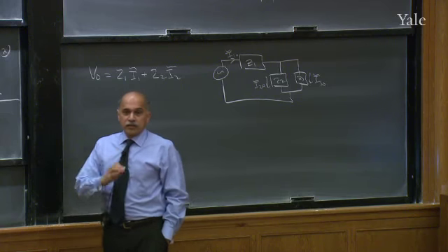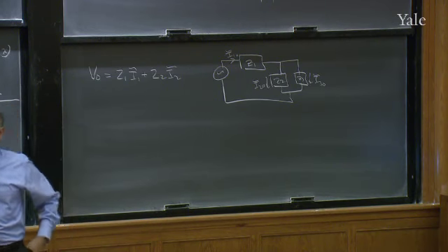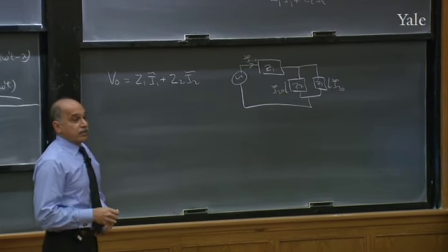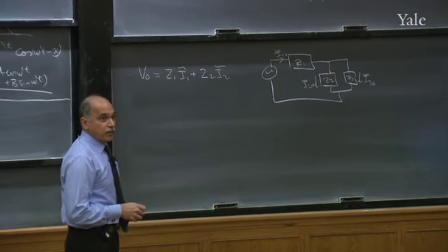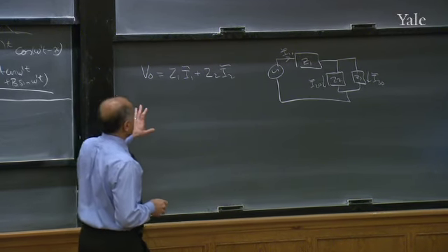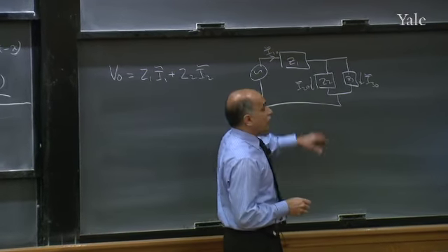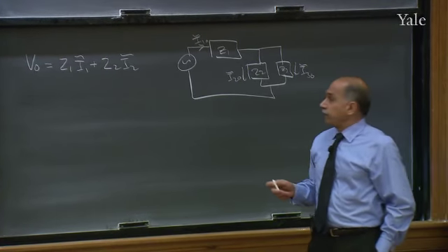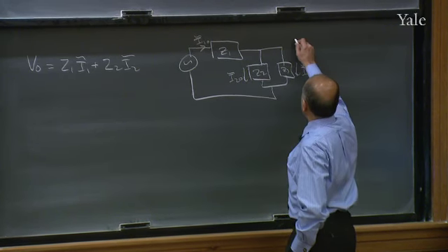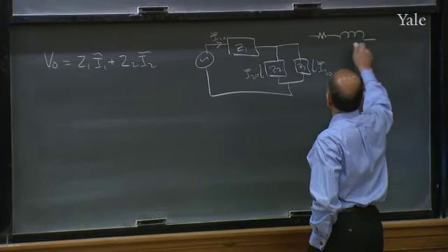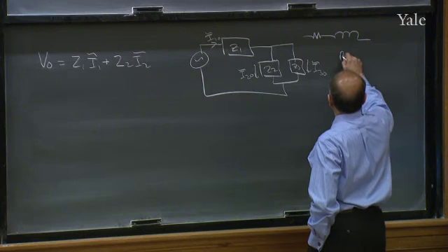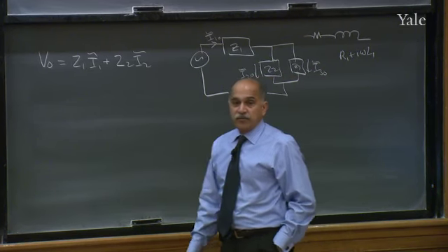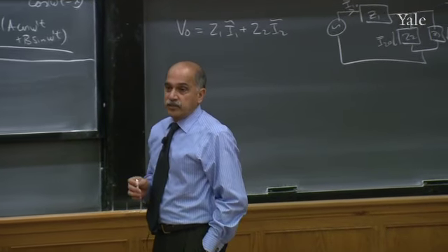And these constant numbers, they have no time dependence, obey the same equations as the real currents did in the real problem. So it's like a DC problem. The only subtlety is the impedances are complex. And the rule for impedance is very simple. If you open the box and you find a resistor plus an inductor, the impedance for that is R1 plus i omega L1. That's it. Apart from that variation, it is just like a DC circuit.